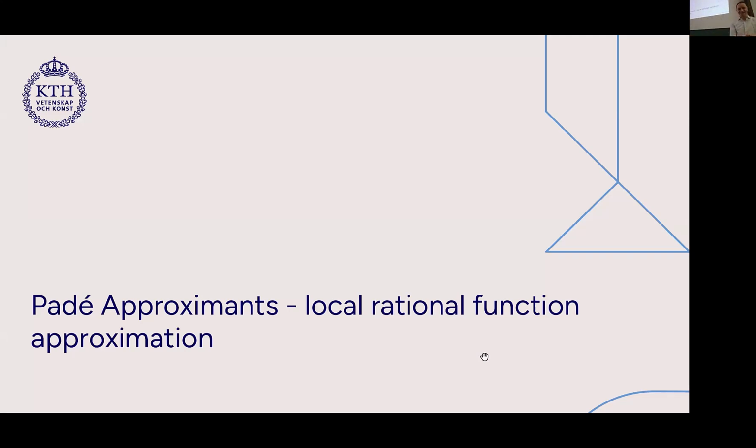Last bit. With modal methods and complex dynamics, as in the poroelastic materials, you have a fairly rigid part of the problem, and then you have the fluid part where many modes can also come from that without a big contribution to the overall response. If you go for the homogeneous problem without directing the efforts toward the actual excitation that you're putting on it and discarding some of the components from the get-go, you end up having this large initial basis to work with.